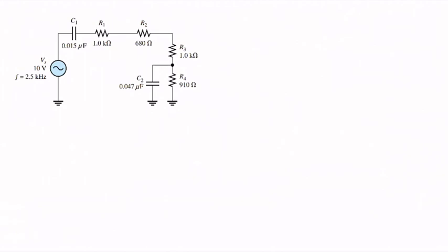So the first thing that we need to do here to simplify this circuit is to get the equivalent circuit for the parallel R4 and C2 circuit elements, and then from there combine them with the C1, R1, R2, R3 to get the total equivalent impedance.